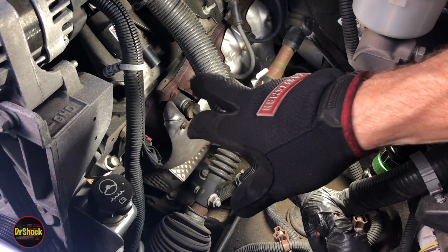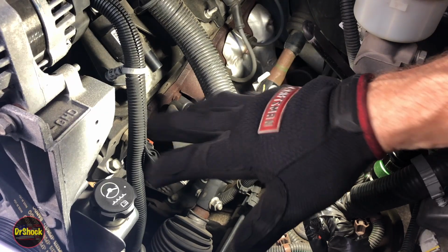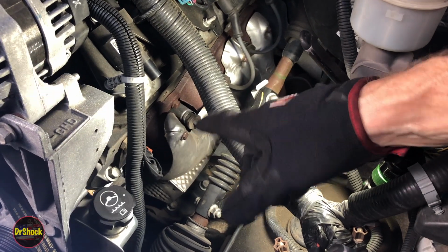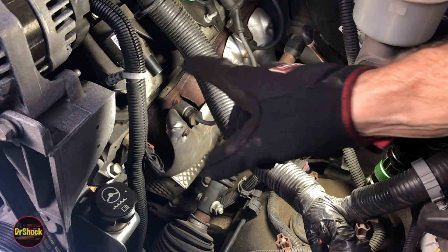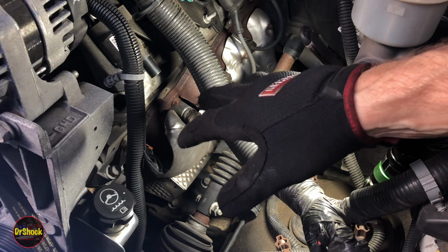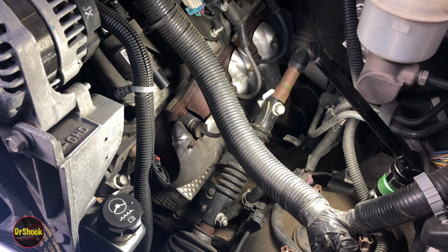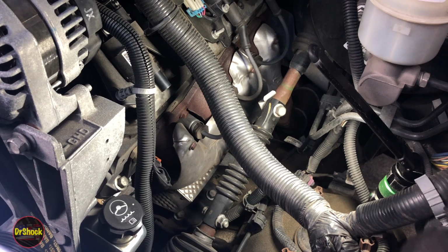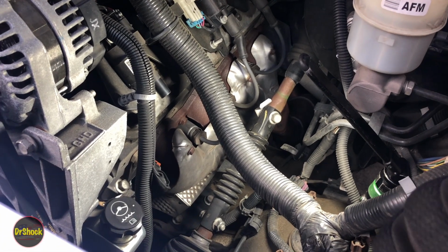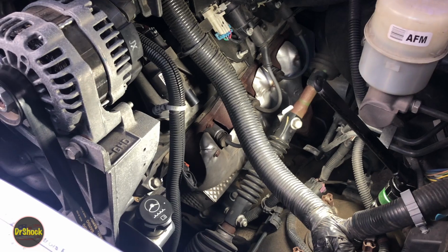But the other thing we can do, all of these ignition wires are the same on this particular engine. And so we could also swap the 1 and 3 ignition wire as some preliminary checks to see what's going on. But for what we're going to do right now, I'm just going to take this new AC Delco plug just for grins. We already know that the old one doesn't look healthy.